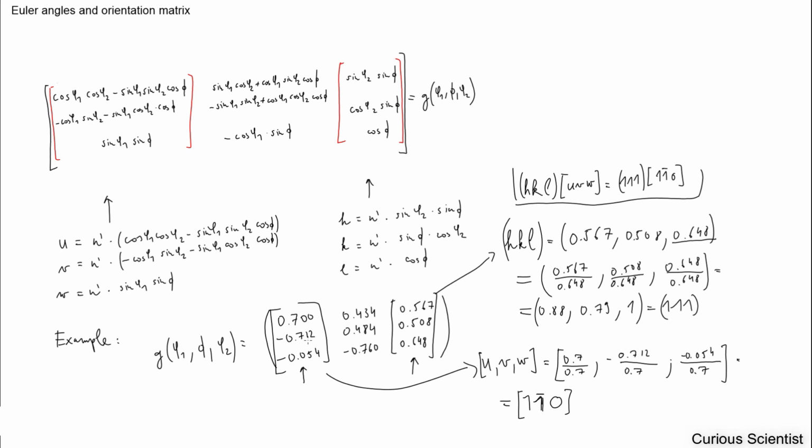It was quite simple. I just showed you the description of the orientation matrix or rotation matrix, how this describes the relationship between the two coordinate systems, which is the specimen and the crystal coordinate system, and then how we can use this rotation operation or rotation matrix to extract more data for our material. And one of these data is basically the texture component.